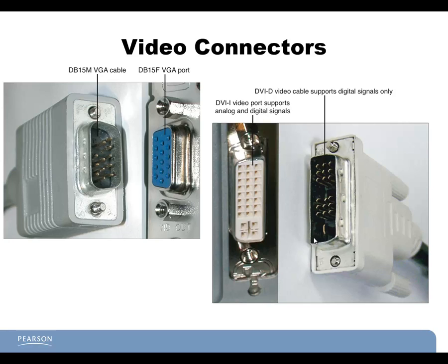If you look at the cable here, they showed a cable that is DVI digital only. And if you notice, instead of a cross, it's got a piece here that's only going to be one way. The way they're holding the cable, this piece is vertical. If this were a DVI both, it would have that where it's a cross, and if it were just an analog signal, that would be horizontal.